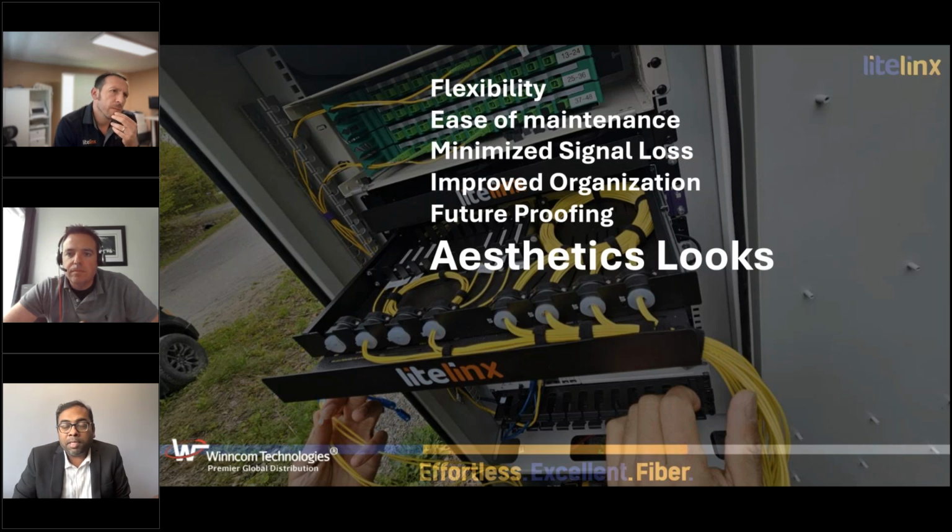So what we do, especially for the cabinets, we try to go everything 19-inch rack mount, and your Nokia is 19-inch rack mount, Calix is 19-inch rack mount, Adtran is 19-inch rack mount. All these ODFs, what we ask them to customize is also 19-inch rack mount. So if you have, let's say, 23U or 25U space in your cabinet and you do a complete 19-inch rack mount there, you are pretty much free to expand these things pretty easily.